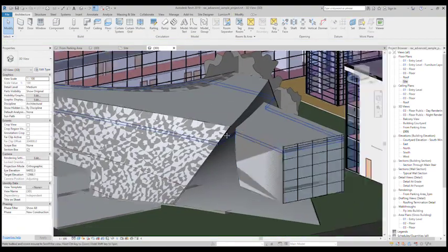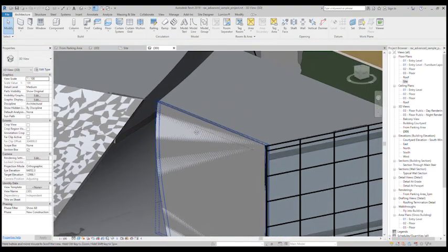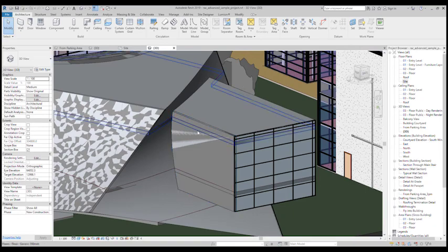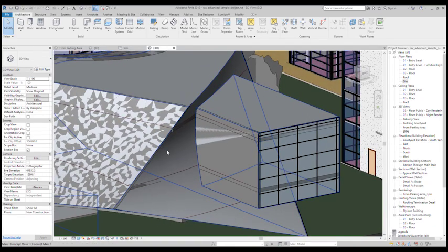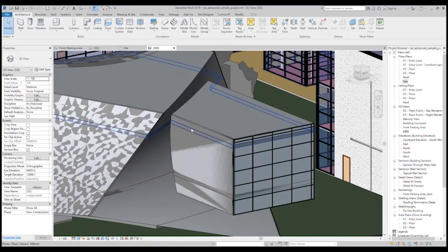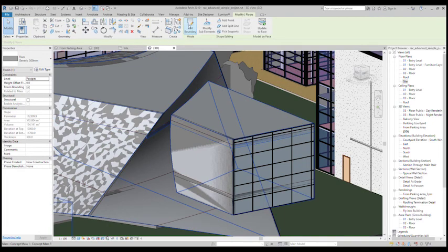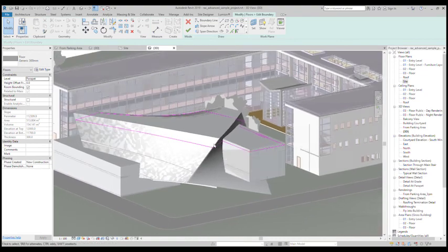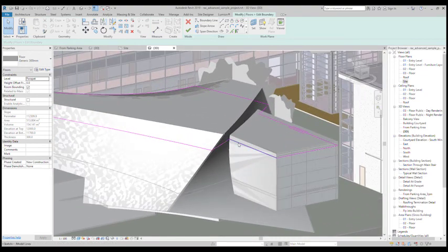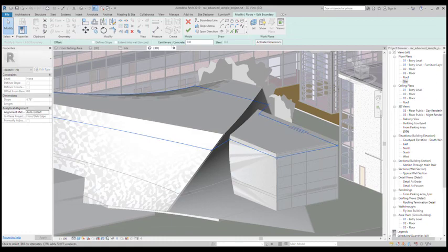So how do we do that with this? There's three ways of doing that. The first is by just placing the floors like we've done now. Then going to each floor, saying edit, clicking on them, edit boundary, hovering over to your boundary, pressing tab once, clicking again, and then where it says concrete cantilever, you add a little bit in there. So for a 230 wall, you have to cantilever 230mm inward.